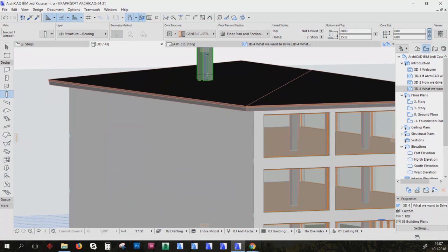So that works on the mesh and the slab as well. If you've got a floor or a place where the floor levels change, using gravity makes it really easy to put walls in place and furniture and stuff like that. So you don't have that situation where you come to look at your elevation and find that the desks are 500 below floor level.